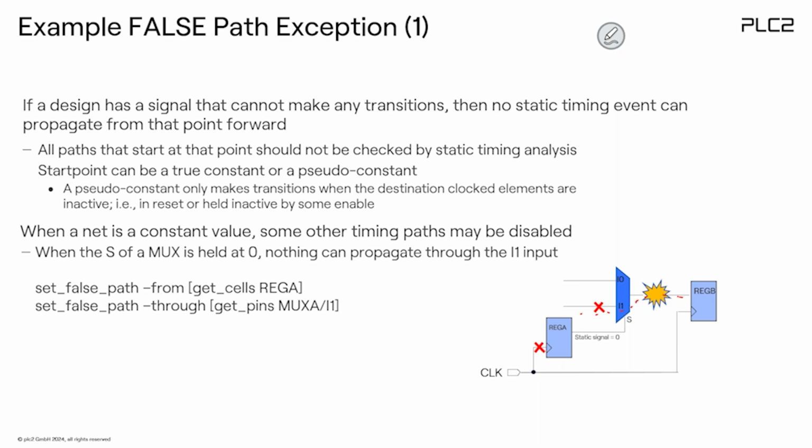That could be very slow because, maybe you change the clock to a slow value, whatever. But then in the real application, it needs to be very fast. Before you start the real application, you just write a 0 in this register. So this register is 0. This path will never be activated because it's a select 1. But you know it's 0. So this path simply doesn't matter. You can say ignore it. That's a false path.